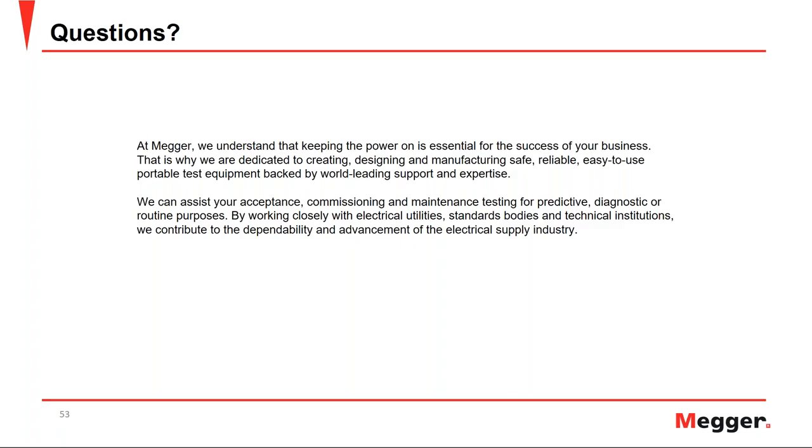One important thing I want to mention here is that it's not just about a negative power factor value. Let's say last time when you did the testing, assuming the temperature is the same, your power factor value was 0.5%, and next year the power factor comes out to be 0.35. I wouldn't be happy about that. Insulation cannot improve by itself.